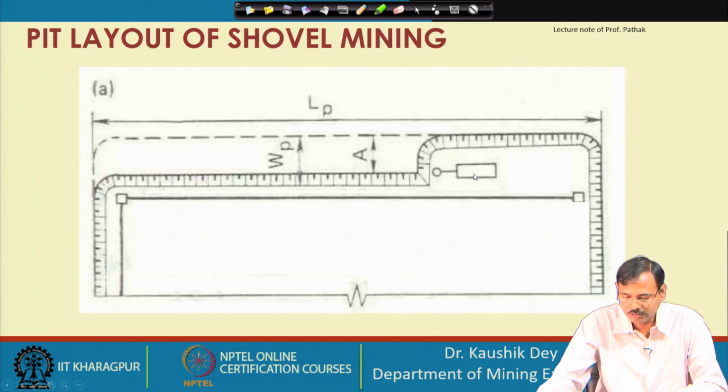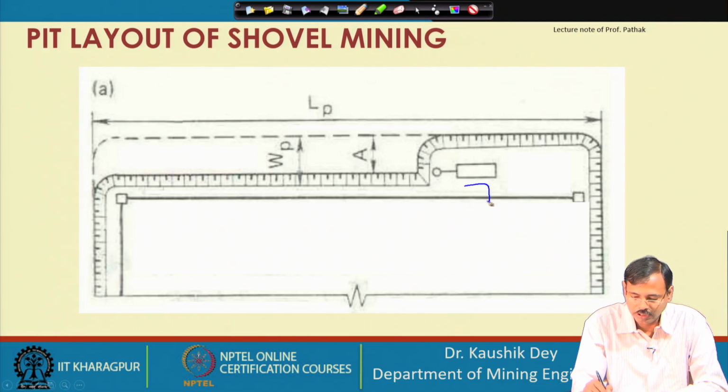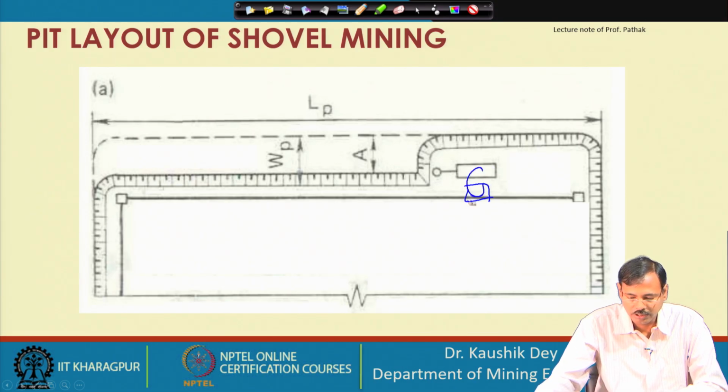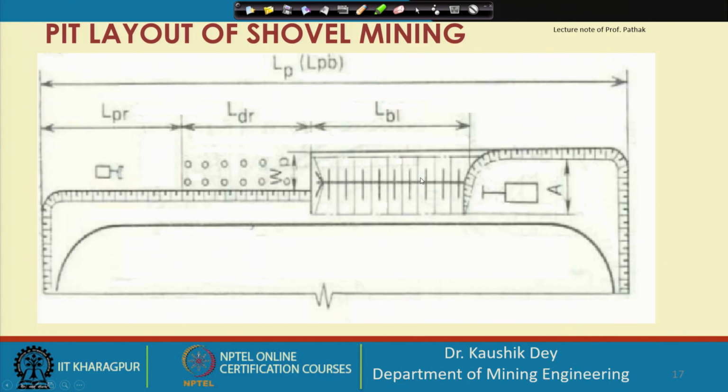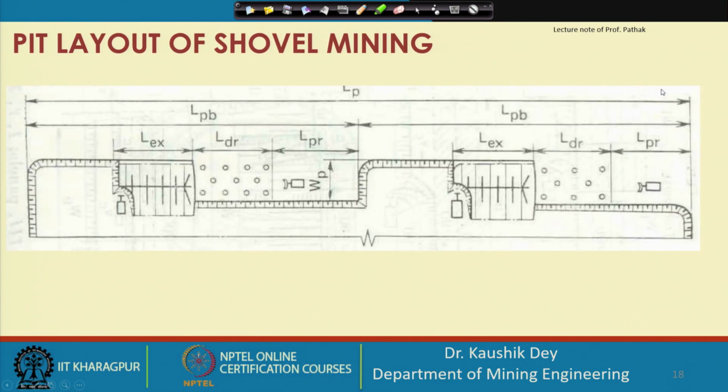Now the excavator is working here and taking the material, we allow our dumper to stand on this and the material is loaded onto the dumper. Gradually dumpers take the material and move out. This is the ramp, provided at this position. Excavation is carried out here and the material is taken out from this ramp in this direction. This is the way we move with our layout.